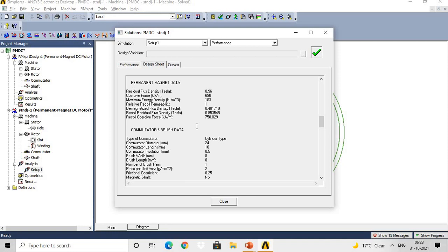But apart from that, you can also make your magnetic study related to the performance of the motor, which is not easy, because in the conventional study method we assume the magnetic flux, then magnetic flux density, etc. But here you can check the performance of this motor related to the magnetic parameters before developing the hardware model of the motor.